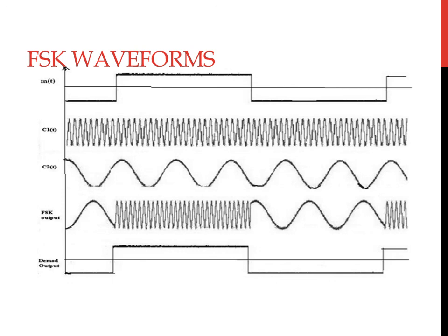So in the detection process we made use of the low pass filter, which eliminated the high frequency components and retained only the low frequency components. Then it was passed to the envelope detector and the comparator. So the demodulated output that you obtained is similar to the signal M of t, but it is a saturated value. So you obtain a peak to peak voltage close to 28 volts. Thank you.